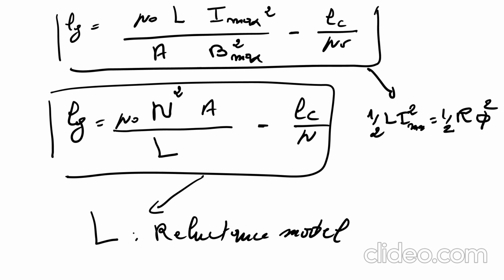The air gap never depends on the cross section, and I will show you why. In the first step, I will show this by intuition, and in the second step, I will give you the correct and exact equation to calculate the required air gap for your magnetic core.